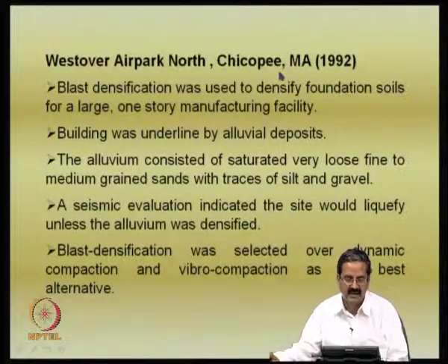Then there is another case study, in which blast densification was used to densify foundation soils for a large one-story manufacturing facility. Here the building has a lot of alluvial deposits beneath the foundation area, and it is saturated very loose to loose fine to medium grained sands with trace of silt and gravel.